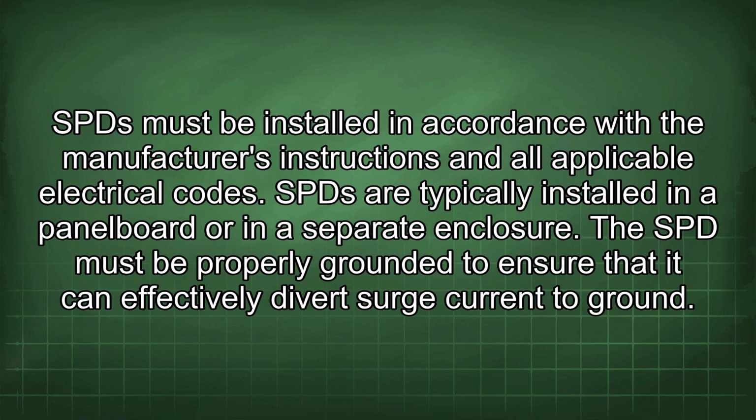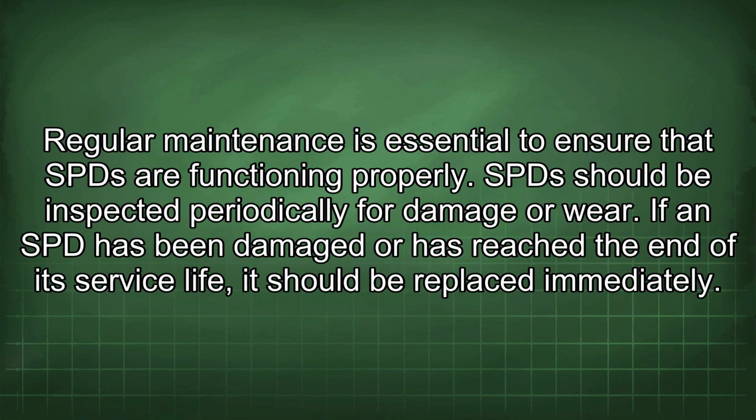SPD are typically installed in a panelboard or in a separate enclosure. The SPD must be properly grounded to ensure that it can effectively divert surge current to ground. Regular maintenance is essential to ensure that SPD are functioning properly. SPD should be inspected periodically for damage or wear. If an SPD has been damaged or has reached the end of its service life, it should be replaced immediately.